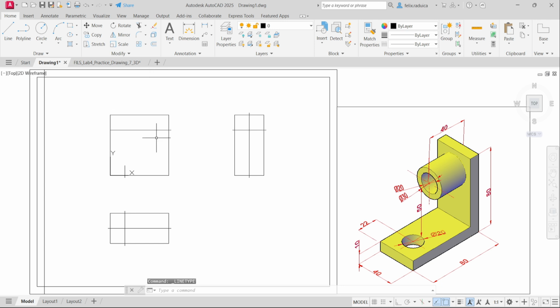Okay, and now I'll select this line to be center 2. And I also want it to be of a red color. And I'll have to set the line type scale, LTSCALE, enter. Set that to 15. And it starts to look like an axis line.